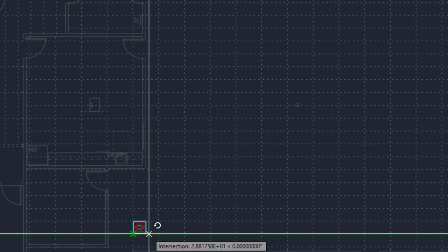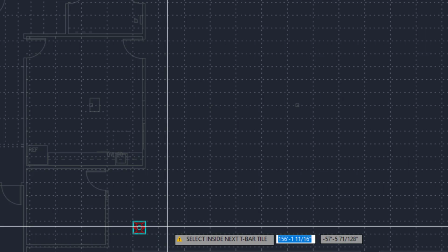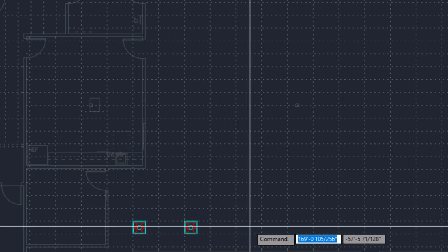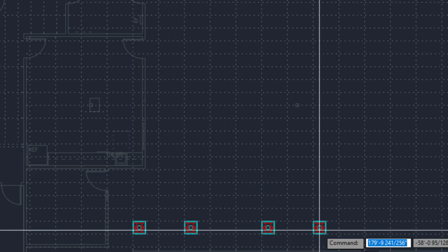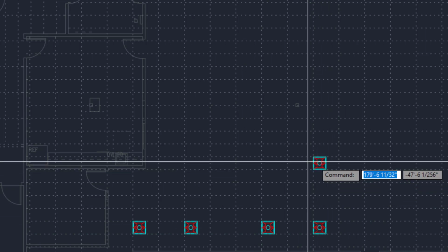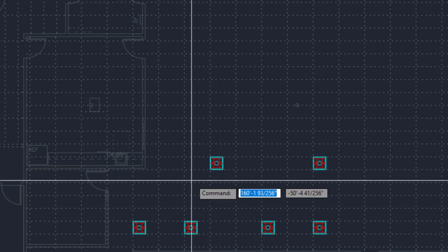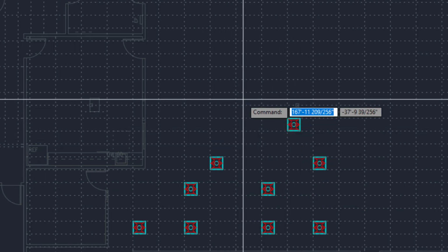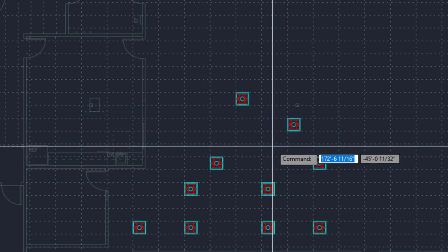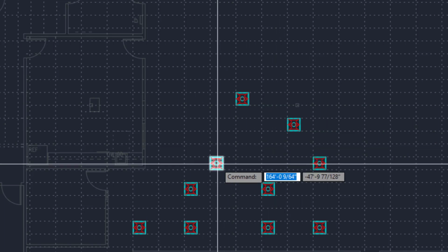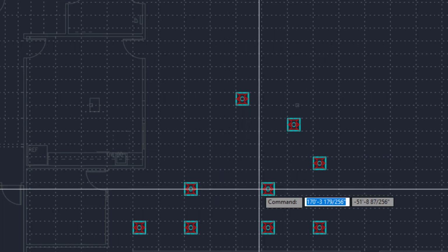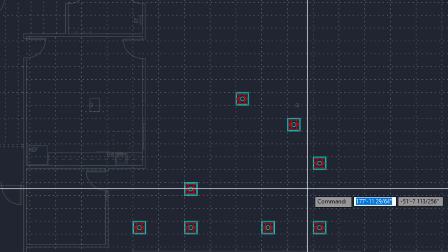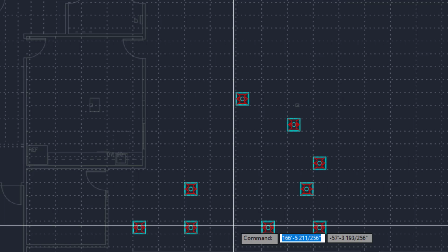So same thing, I'm going to give it the intersection, give it a rotation, and now I'm selecting, but as I come up you notice it didn't copy it by row, it just is multiple. So you can do different patterns. We used to do checkerboard patterns 20 years ago. I don't think we've done it in a long time, but something like that. And if you want to take one out, you just select it again and then put it back in somewhere else, and it's pretty quick.